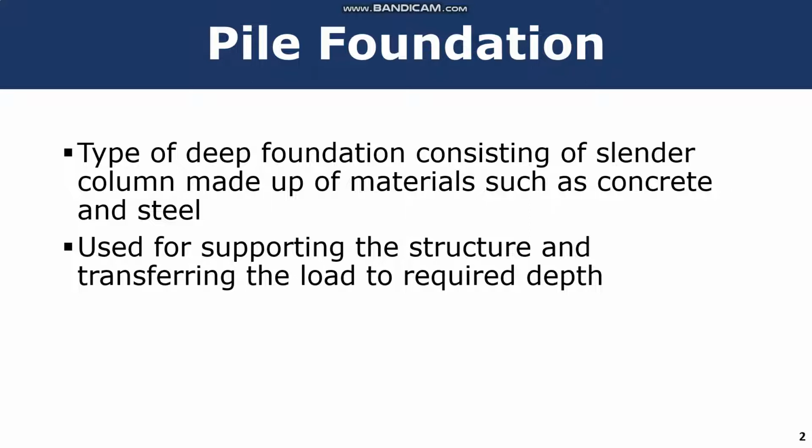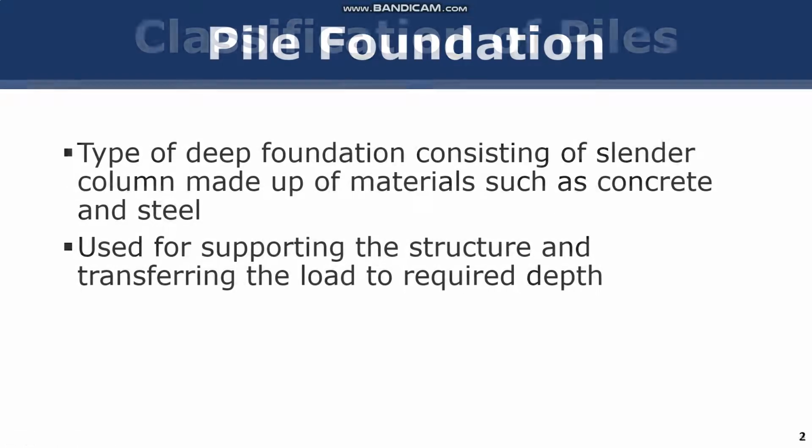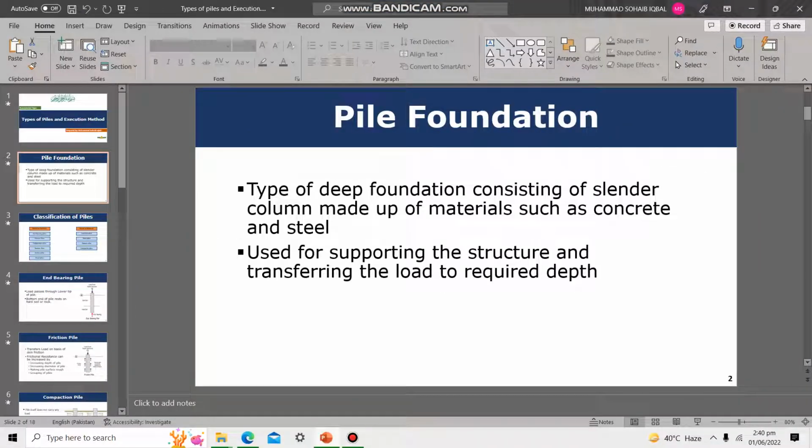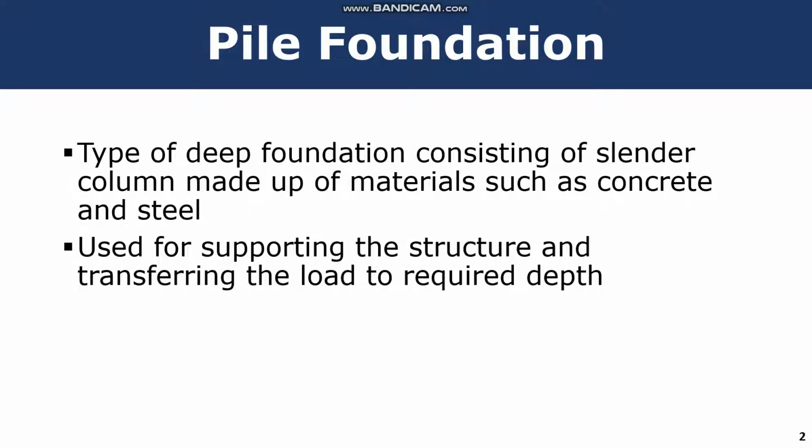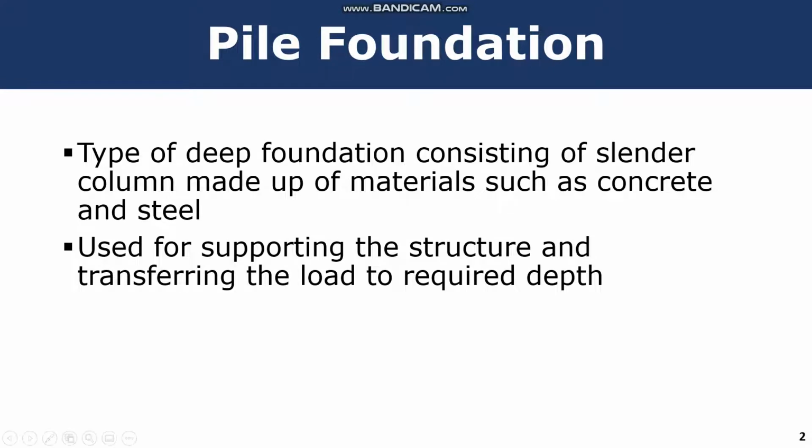So when we talk about pile foundation, it is basically a type of deep foundation which is utilized when the top portion of the soil is weak and there is a need to transfer the load to the required depth where the soil is hard enough to take the load coming from the superstructure. So it is a type of deep foundation. Its length to width ratio is greater than 2.